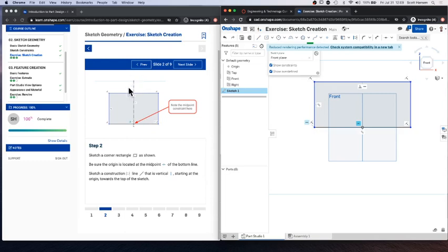The next thing we want to add is this line going through the middle of our rectangle. So I'm going to go up here and select the line tool. The keyboard shortcut's L on your laptop. So I'm going to click one point to the line, click another point to the line. Now, you can keep clicking again and make like a bazillion lines.